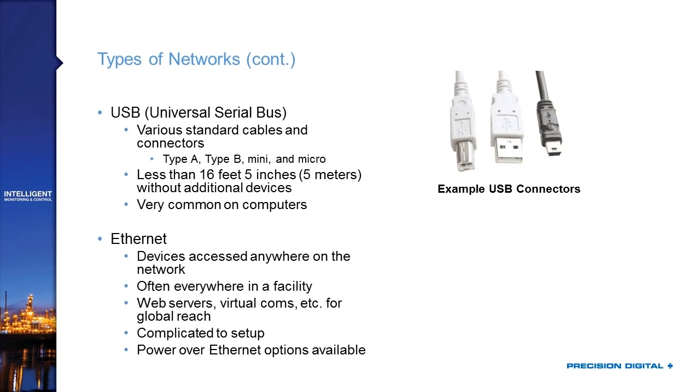USB is also a great choice if you get an RS-485 to USB adapter, because then you can wire your field devices with RS-485, bring that into your adapter, and then take out USB that connects to your computer.